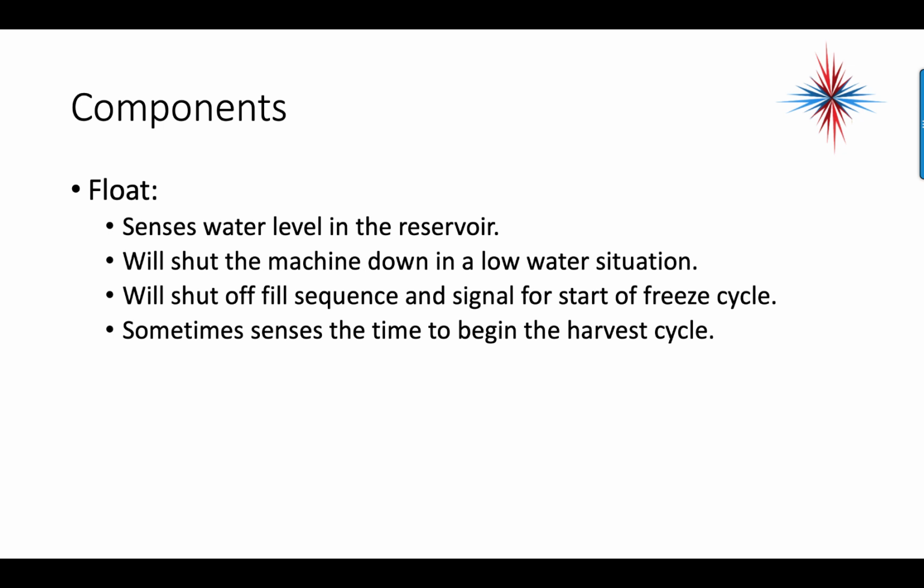There's a float. It senses the water level in the reservoir. It will shut the machine down in a low water situation. It will shut off the fill sequence and signal for the start of the freeze cycle. It sometimes senses the time to begin the harvest cycle.